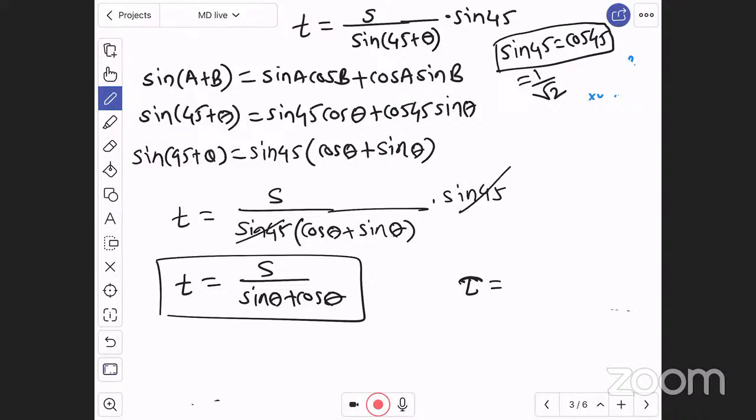The failure is because of shear stresses. Therefore, shear stress is nothing but load divided by area, which is nothing but load divided by shear area, that is T into L. This thickness, throat thickness, the failure plane thickness, we have to consider. Now, in this case, the failure is always because of the maximum shear stresses.